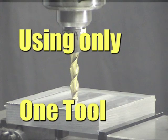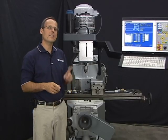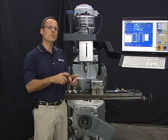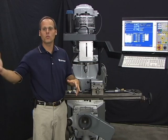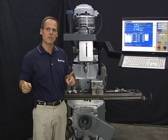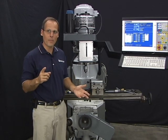Another little trick I'd like to tell you is if your program is only using one tool, it is not necessary to measure it against the reference tool. The reference tool is only really necessary when your programs have 2 or more tools in them, so the control knows the difference in height between the tools. Well, if your program only has one tool, there's nothing else to worry about.